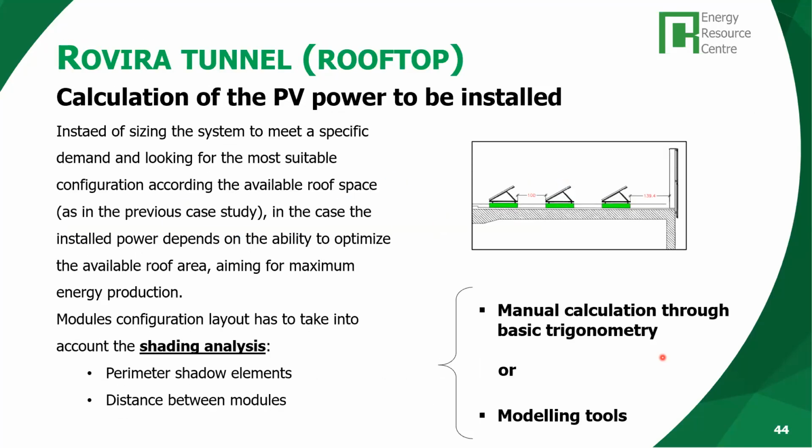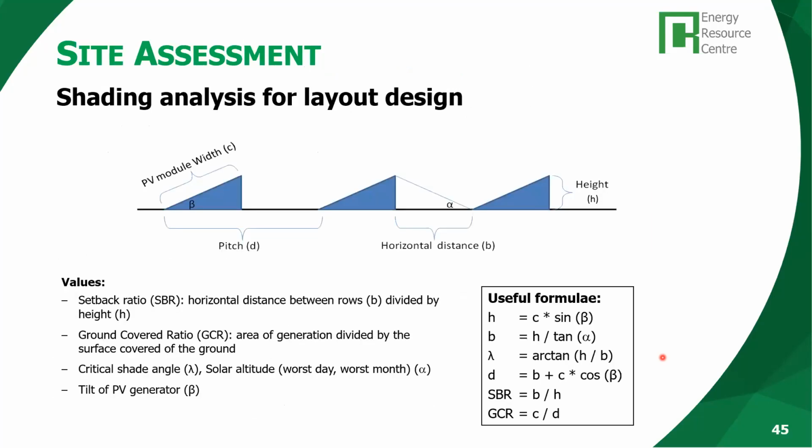Yeah. So remember, ladies and gentlemen, we did this exercise in session PV05, where we mentioned how you can do it with trigonometric calculations. Yes, exactly. How to optimize the distance, because obviously when the sun is low, remember, the sun will hit our first panel, and the first panel will necessarily be shading the panels behind it.